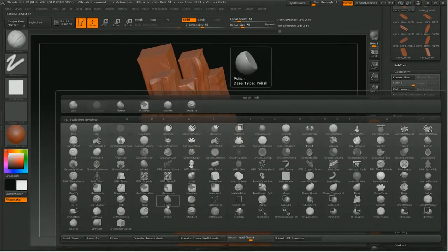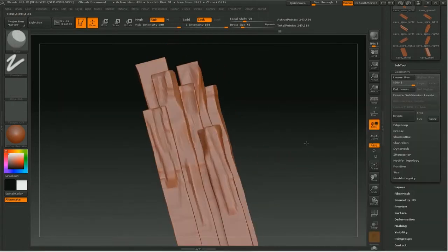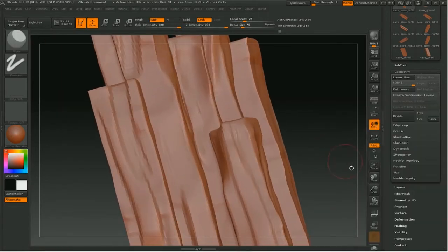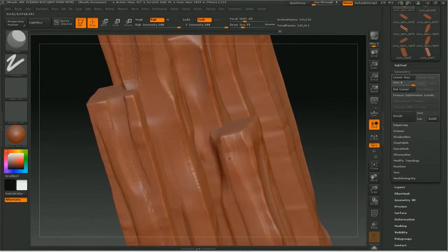And the planar tool is one that I use a lot. Once you have some of this height variation, you can come in. And again, I like to switch to the square alpha channel, just so I'm keeping these hard edges. Depending where your initial selection is, it'll take a sample of that area and then try to continue a flat plane based on that initial sample. And if you hold Alt, it'll grow areas as opposed to carving them out.